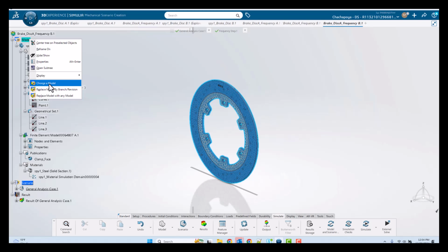They exist for simulations that are somewhat in the logical world where they're not associated with the physical product. Logical simulations, kinematic simulations, they don't work based on a physical model. They have their own product structure. So these two options exist for different types of simulations, but not exactly for physical simulations like FEA and CFD that we are setting up.